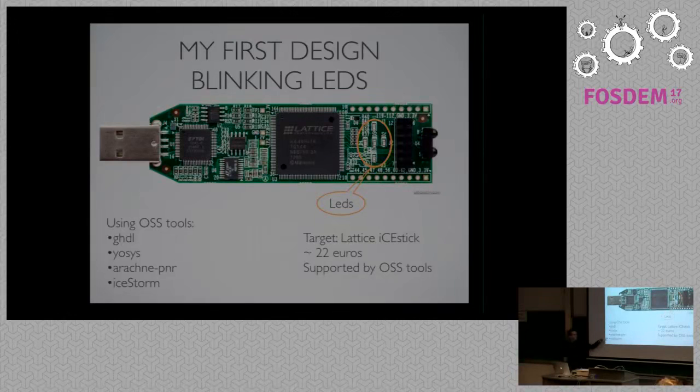There is a place and route tool, I will explain that later, named arachne-pnr. And there is IceStorm, which is used to create the binary stream to program this circuit. This board is about 20 euros, so very affordable, and it is supported by open source tools. So it's very nice for beginners.